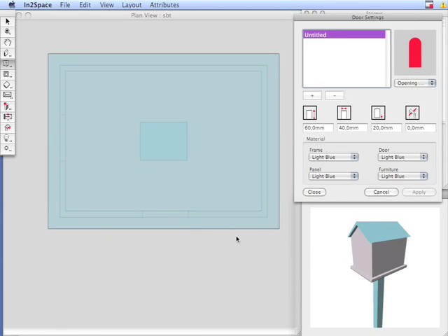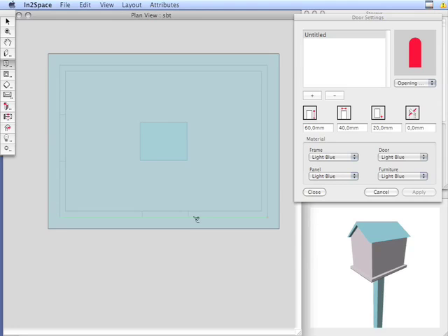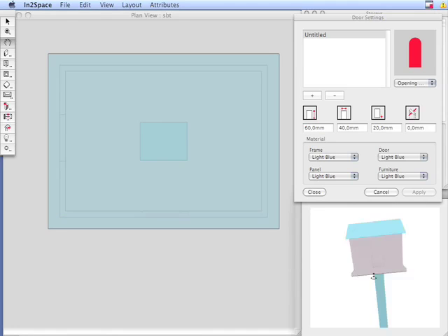Having selected that story, or that layer within the story, again this clockwise convention, if we click on this point, the hole will be positioned there, and it will travel in this clockwise direction. And there is our first aperture. Because we're parametric, we can change those sizes completely on the fly, like so. I'm going to set that back to 60.